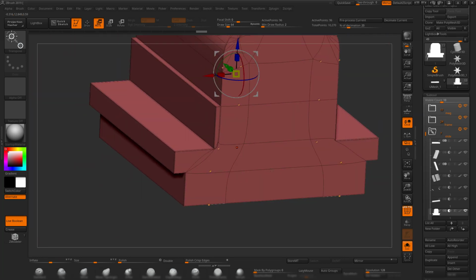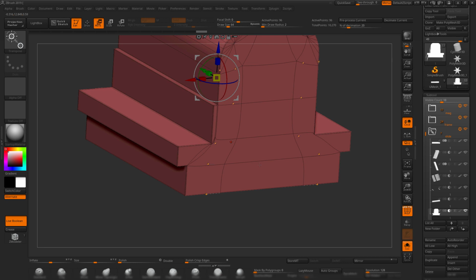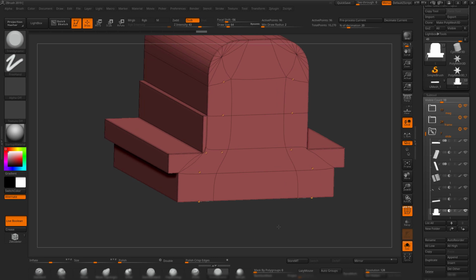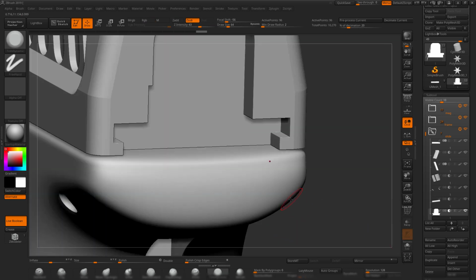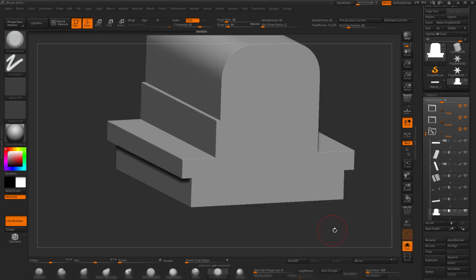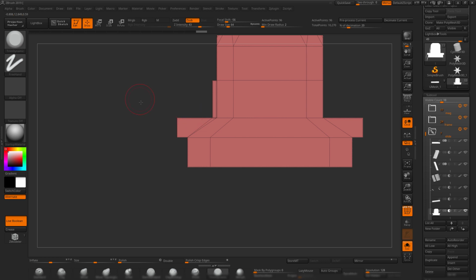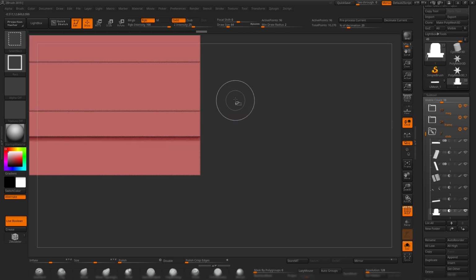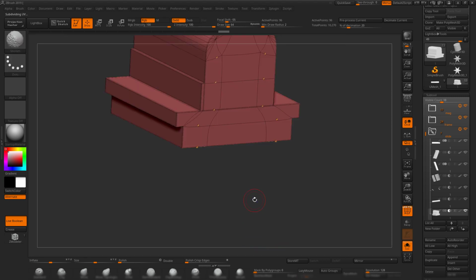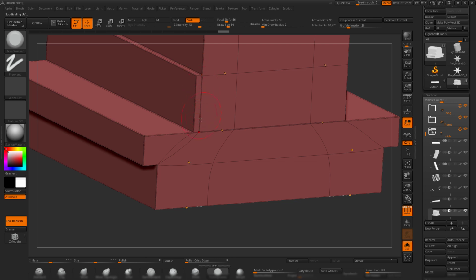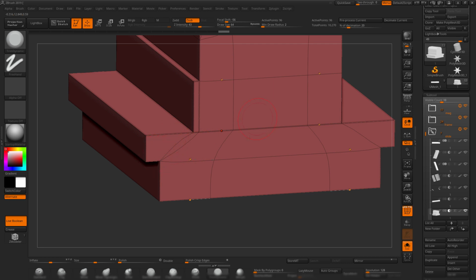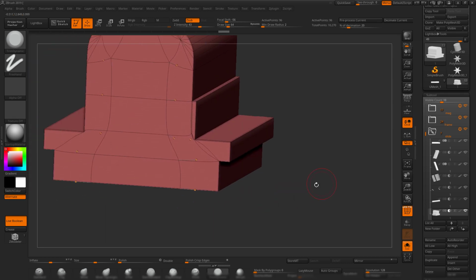That's because of the conflict between creasing and the topology of the object. Basically there's nothing bad about it. It's just you can get some errors while previewing booleans. If you want to fix that, you just crease the hell out of this part so that everything will be creased like this. So you can see I just added this crease over here and this, and it chilled down this topology issue, not like here.